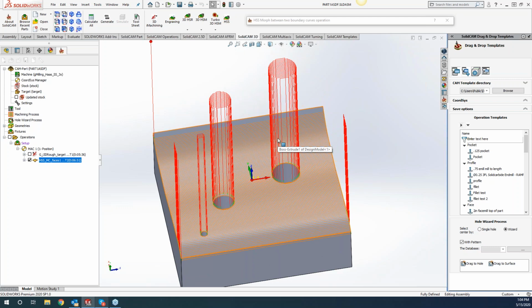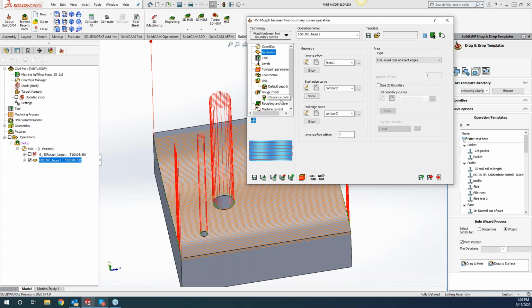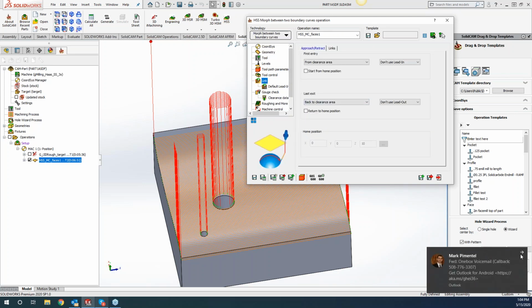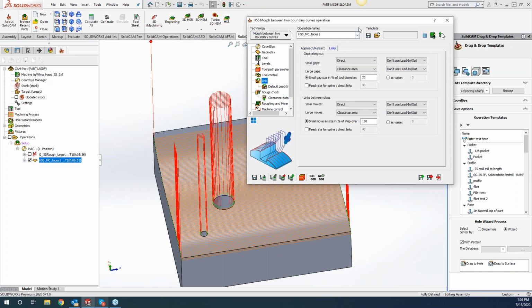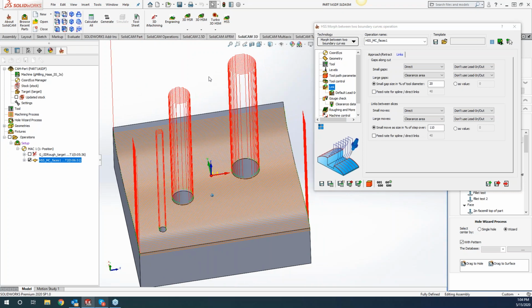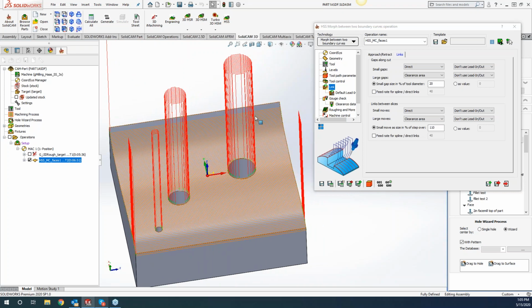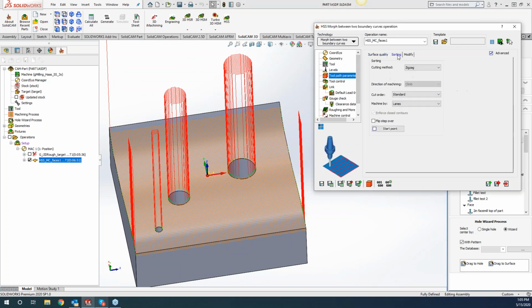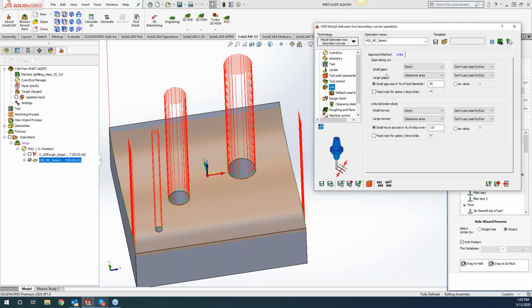Now, we can go about this two different ways. We can go into our SolidWorks and fill those holes in using our surface feature, or we can just tell HSS to imagine that there was a surface there. To do that, you go right over to your links page, and click on the links tab. This is where I pretty much go all the time if I have any kind of retracting going up and down. We are doing a constant geometry, just a zigzag going back and forth here, but we want to control those retracts.